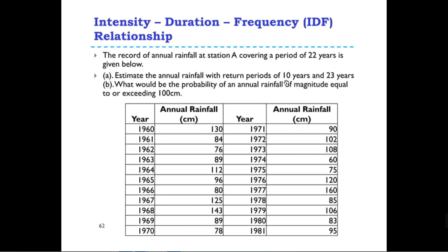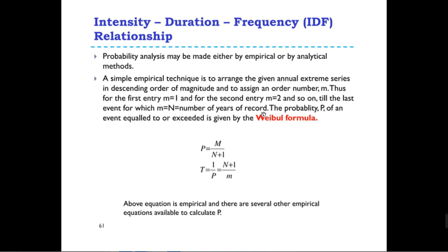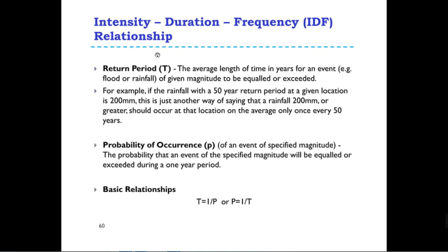First of all, you have to understand the meaning of return period. Return period means the average length of time, in years, for an event, flood or rainfall, of a given magnitude to be equaled or exceeded.